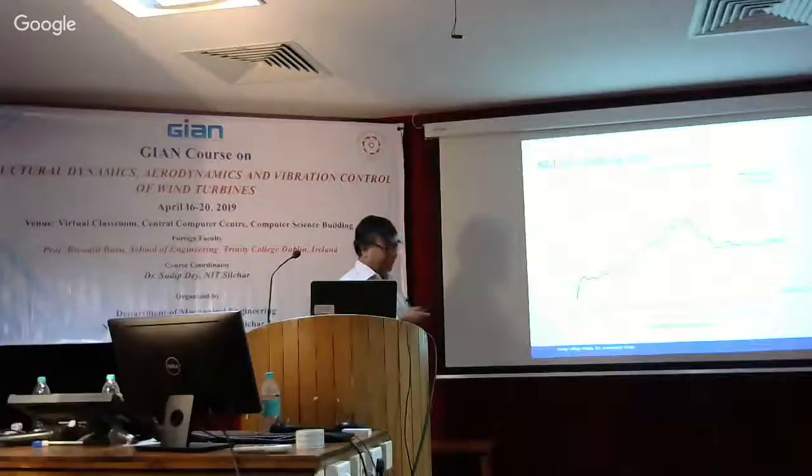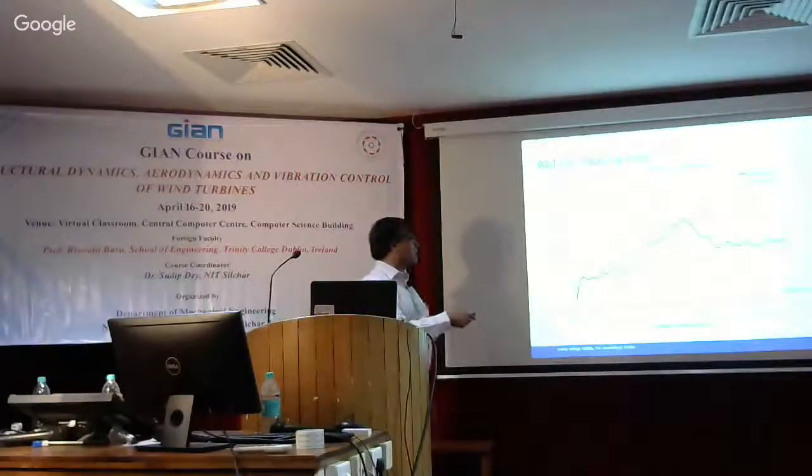And the effect of individual and collective pitch control can be seen here. With the collective pitch control, this is the bending moment profile you have, and with the differential pitch control or individual pitch control, you also have additional beneficial effects.